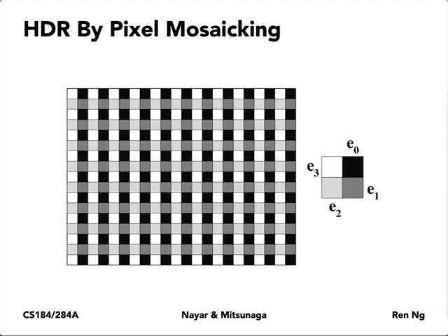The proposal is to have little darkening filters in front of the sensor pixels. You can see the pattern. Okay, so this one has no darkening filter. And then this one's got one that's a little bit darker, much darker, and then quite dark, maybe one stop each time. So spanning 4 stops of exposure duration, or 4 exposure light levels.